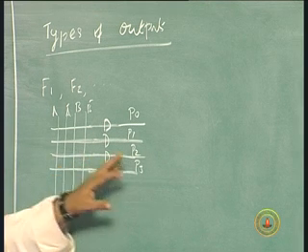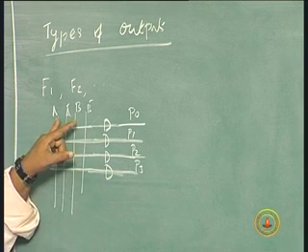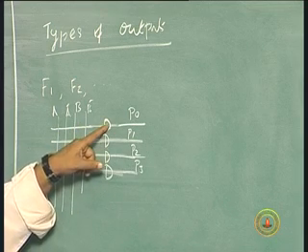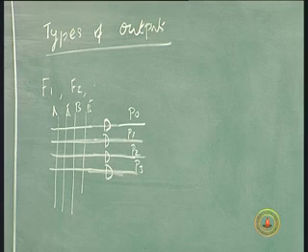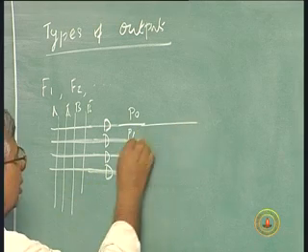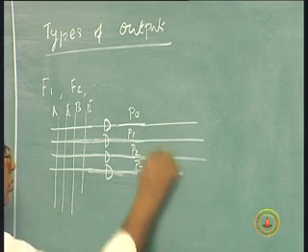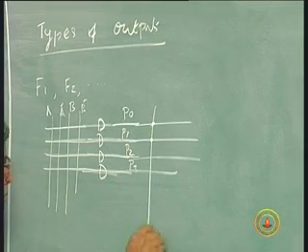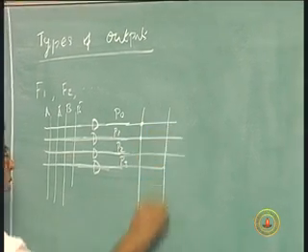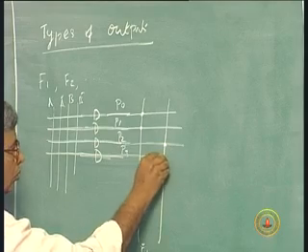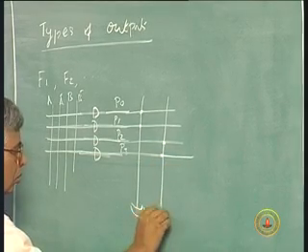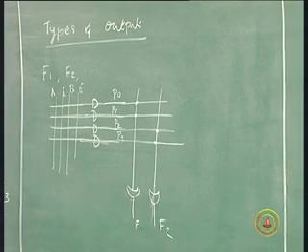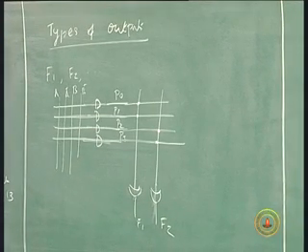They represent this to tell you that there are two inputs possible and 4 product terms possible. Each of these product terms can be functions of A, A bar, B, B bar. And then of course, there will be a third one which will tell you this. This is my F1. This is a pictorial or schematic representation of the PAL.